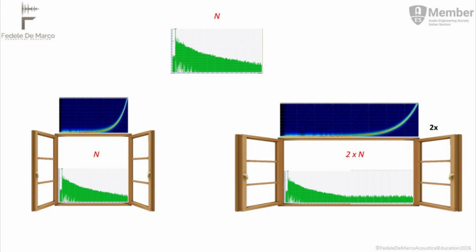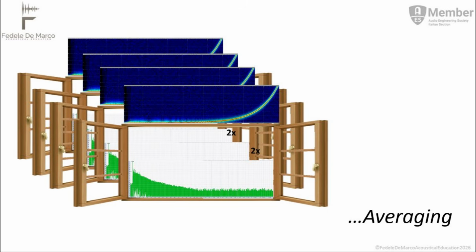You must ensure, and in acoustic work, for example, the standards themselves mandate it, that ideally, both the duration of the test signal and the measurement window adequately include the entire decay of the room. This is essential if you are interested in studying the room itself, or the interaction of a sound system with it. In fact, for many works, standards require them to be 2 or 3 times the decay of the sound phenomenon you are studying. It is common to raise the SN ratio by averaging measurements. However, this method is not without its limits and trade-offs.